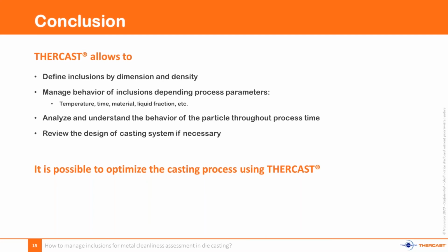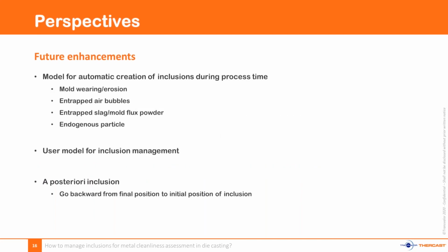But as always, it's not but, it's a fact. As always, we are trying to improve again and again our proposition for the customers, and that is why we have some perspectives in order to improve again this model and feature. So we will add some models in order to automatically create inclusions during the process time, with different rules. Some of them are that we will take into account the mold wearing or erosion during the process, in case of sand molds or core.